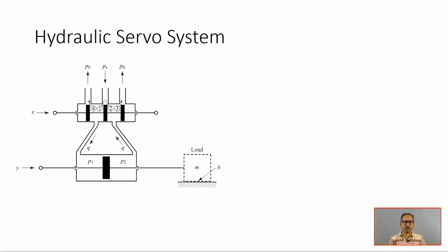So, the maximum pressure in hydraulic power systems can go up to 700 bar or 70 megapascal. Okay, but that is the extreme case. Usually we prefer the maximum pressure in hydraulic systems within 350 bar or 35 MPa. Such a high pressure can be maneuvered, and very high power systems can be used by means of this hydraulic pressure, which originates from Pascal's law, which all of you know. It is the very beginning of power systems, the underlying concept is Pascal's law. Okay. So, in this particular figure, the hydraulic servo system is displayed.